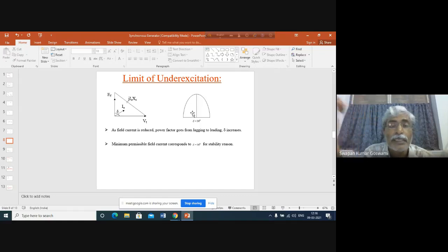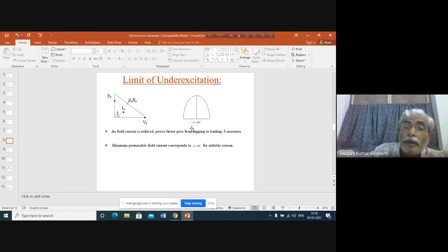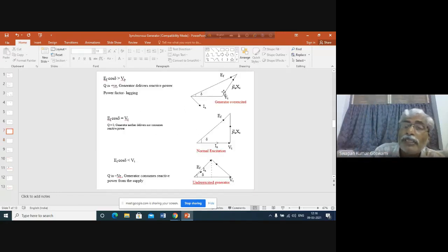Am I clear? বুঝতে পেরেছো? Yes, sir. Okay. Now, how much you can increase the field current? এটা হচ্ছে মিনিমামটা বোঝা গেল, তাহলে steady state stability will decide the minimum value of the field current, sorry, under excitation limit. Okay. But if you increase the field current, you can deliver more reactive power.